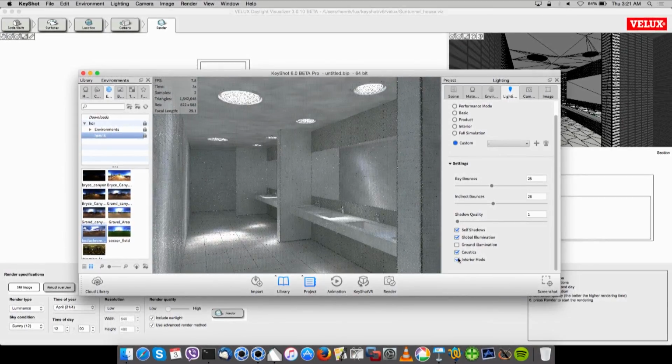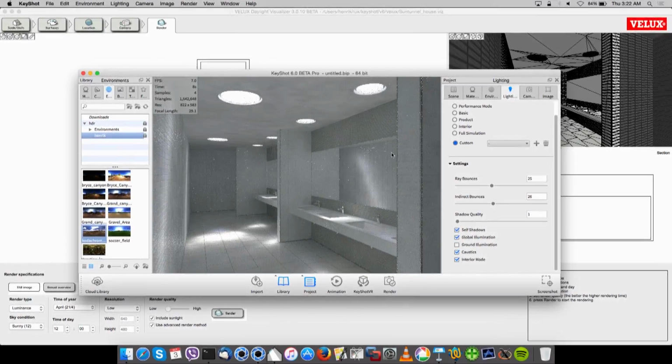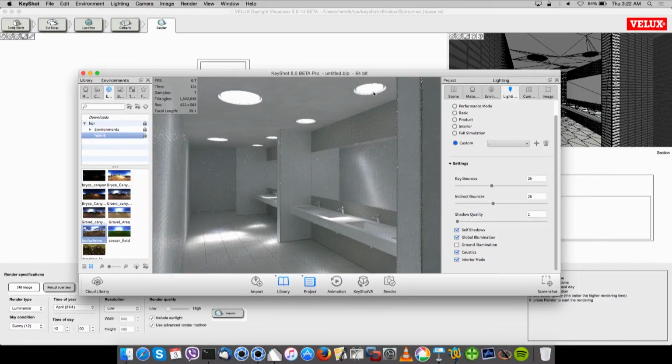And again, it's running on a laptop, and this one is not as fast as it could be because we actually use some pretty sophisticated things. The sun tunnel is all metallic inside, and then there's a diffuser on the front, but it's not a simple diffuser. Velux again wanted it to be accurate, so we did a measurement of the actual diffuser material. It's a full measurement in a gonio reflectometer of the light scattering by the diffuser. It makes it a little bit slower to deal with.